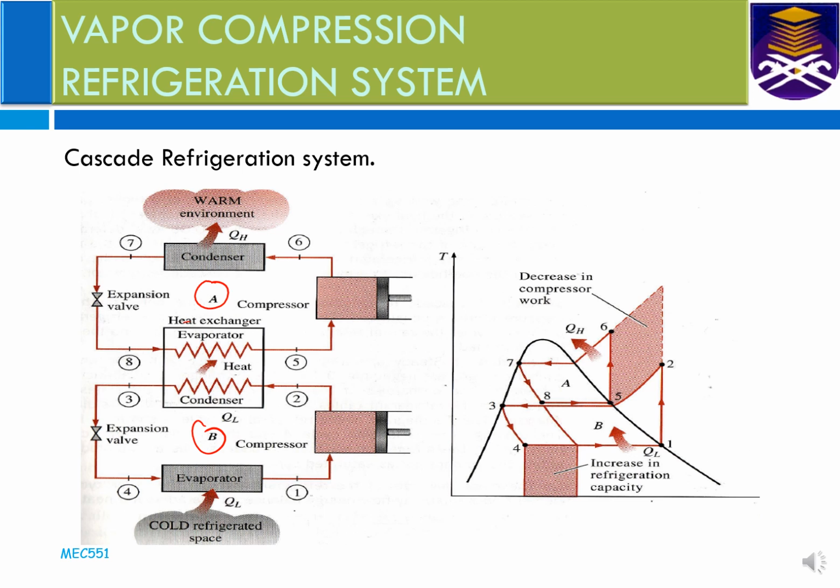So for example, if we have this temperature entropy diagram, what we have here is, starting from state 1 in the compressor, we go to the condenser of the bottom cycle, where we reject the heat in the heat exchanger, and the evaporator of the top cycle in the heat exchanger will absorb the heat.